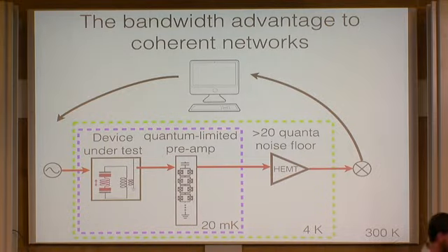One of the main ones is probably going to be a bandwidth advantage. In any experiment, even ones that don't close the loop up here, look like this to date, basically. You have something you're measuring. You actually have to home build an amplifier that either achieves or comes close to achieving the fundamental quantum limit for amplification of electromagnetism. And then that gets a little bit hotter and it goes to this commercial thing called a HEMT amplifier, high electron mobility transistor. And while it's very good, if you turned its noise floor into quanta of energy, it's something like 20.